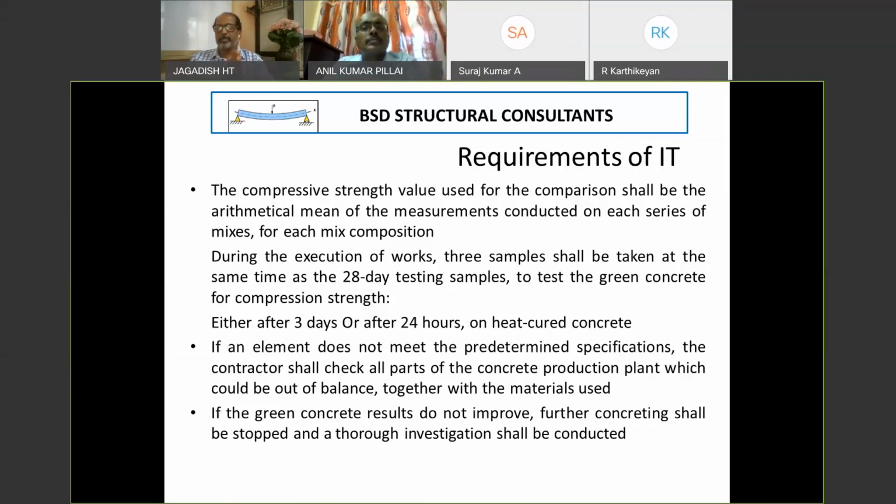We have to ensure that there is no release of activity from the reactor building to the people outside. That's the foremost important thing to keep in mind in a nuclear power plant. So for concreting, whatever we do as per the RCC-G code, quality control and quality assurance measures are always in place. Even while placing, we take care that the concrete is compacted properly. If we find any problem after deshuttering, we simply dismantle that structure and redo it, as simple as that. There is nothing called repairs. Minor repairs we can do, but if there's a major problem, just dismantle and redo it.